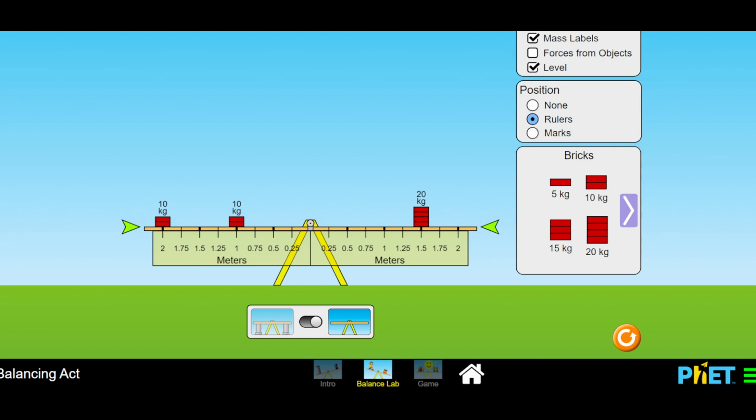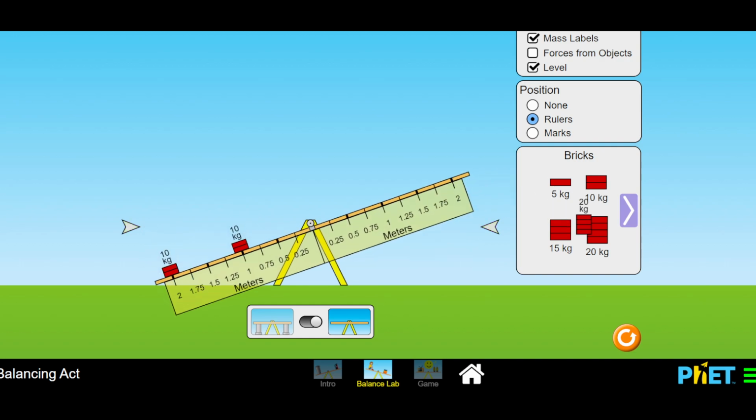But how do we get this? We can't do this by hit and trial again and again, so how do we do this mathematically? In order to do that, we're going to use the principle of moments and use that idea to make the equation for this system, and then try to place this 20 kg mass exactly where it's going to come out mathematically, right?